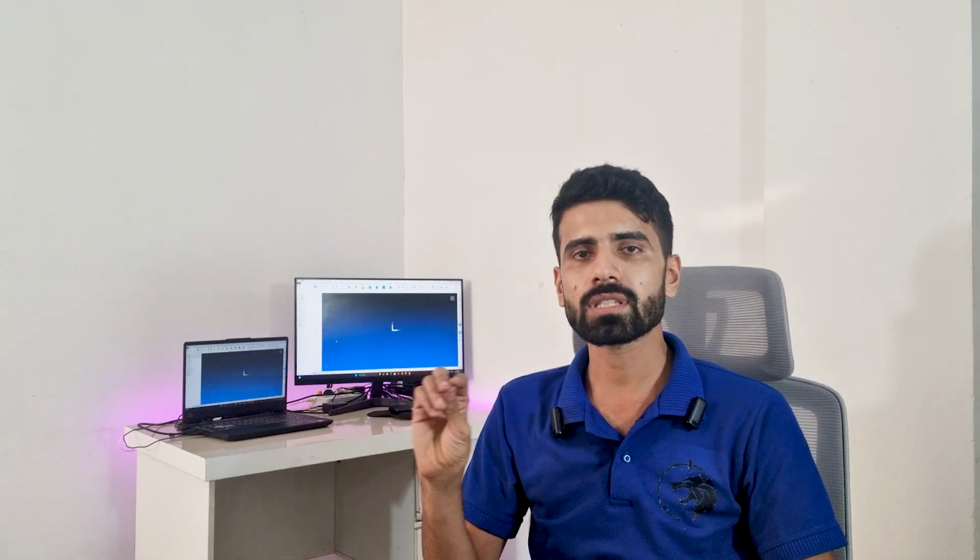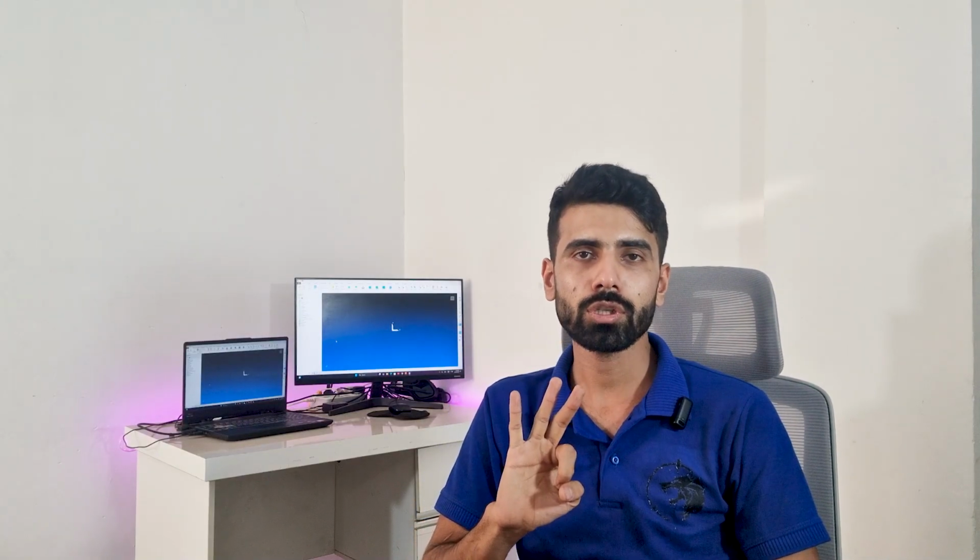In that case, we have several situations. We have some different situations, which depend on our status. We're going to choose the one which is suitable to our machining. We have three kinds of rest machining which are usually used in machining or in programming in Powermill. Number one is use with rest boundary, for the most simple models. As we talk about it, I'm going to show you how.